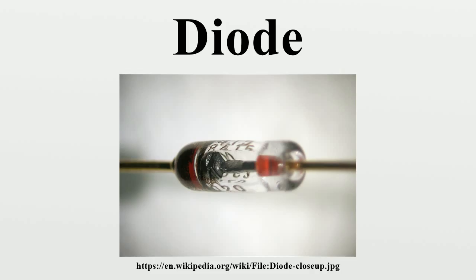The cathode is coated with oxides of alkaline earth metals such as barium and strontium oxides, which have a low work function, to increase the number of electrons emitted. The alternating voltage to be rectified is applied between the cathode and the concentric plate electrode. When the plate has a positive voltage with respect to the cathode, it electrostatically attracts the electrons from the cathode.